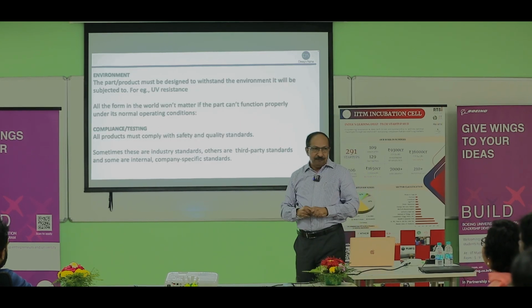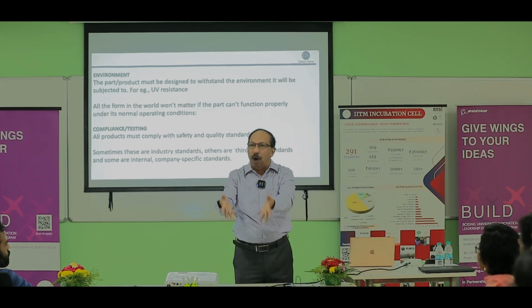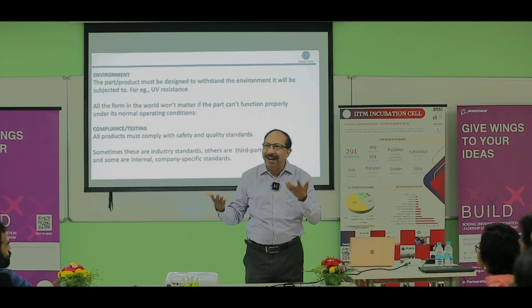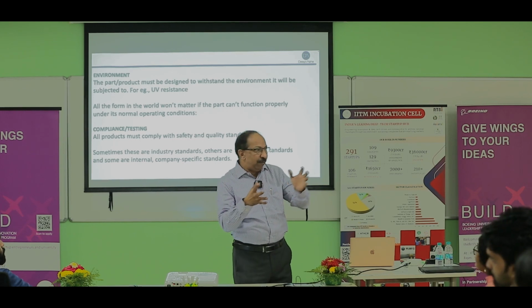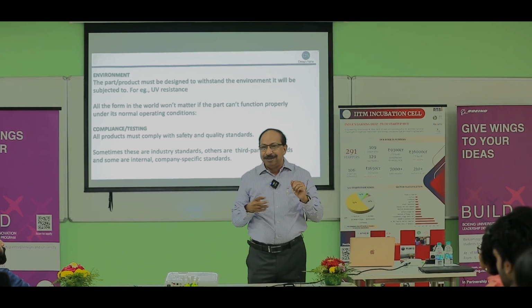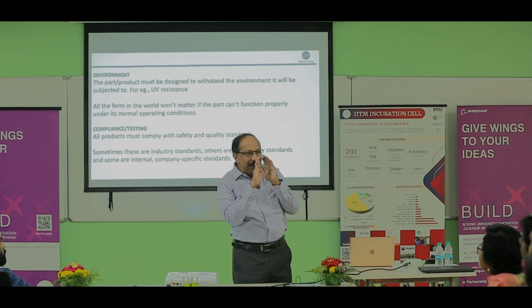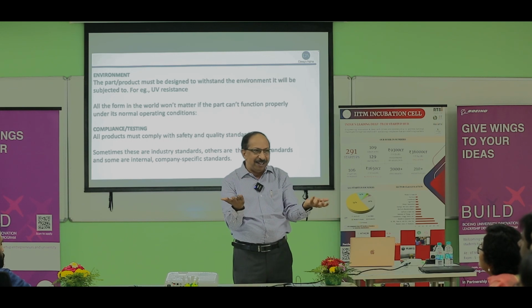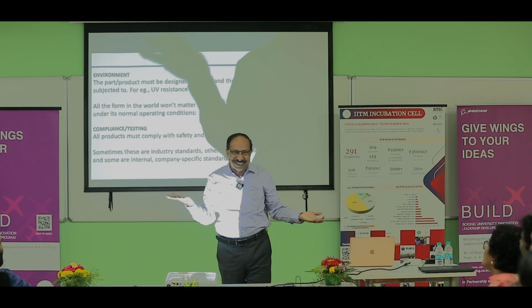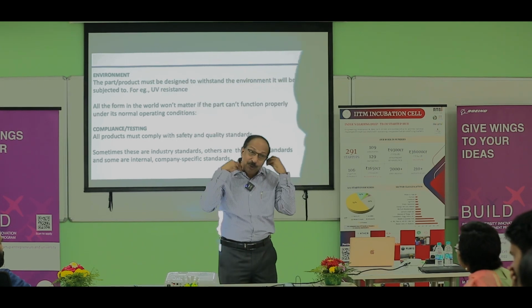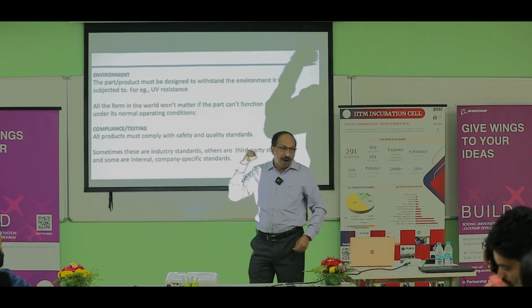Then environment, where this is going to be installed. For example, if you are going to install something underwater, corrosion and all those things will happen. So how are you doing the design? What material are you going to use? Another case, you are going to put it in sunlight. When you expose it to UV light, direct sunlight, after some time it will become brittle and break. You can see on many posts, many of the boxes hang like this. That is because of that. So you have to take care of that. What material is UV resistant? That is how you have to take care of it.